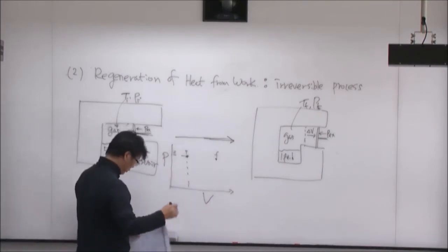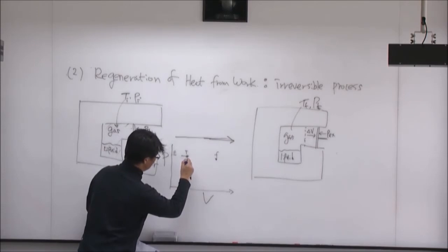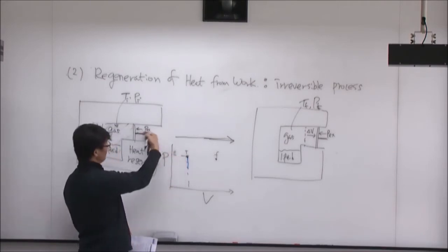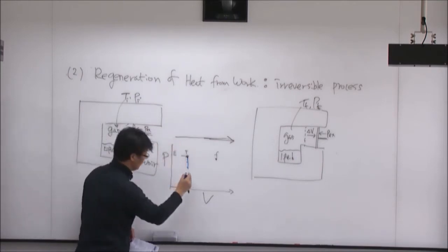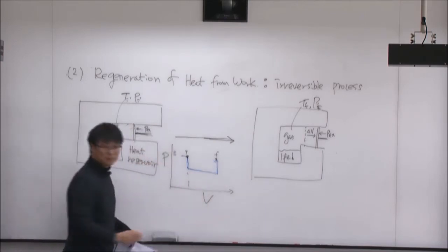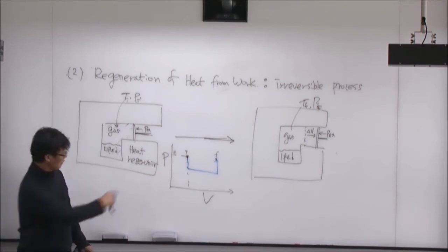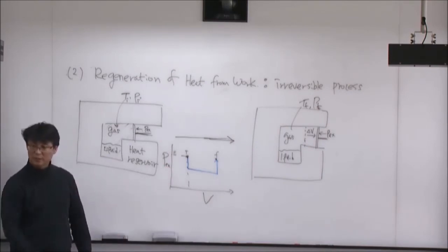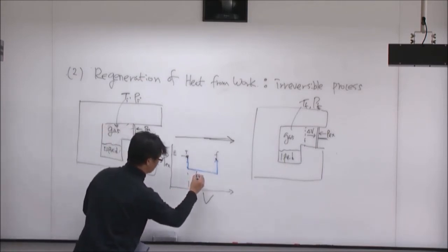Then I can have two different kinds of process. So I can have it like this. So in the beginning, I have P1 pressure, but I drop my pressure very quickly outside here. P external is dropped. So this can expand very quickly. And then expand, and then going back. So my pressure is maintained as the same. Okay? So typically this is P external. I can make this kind of process. And this is, for example, an irreversible process.